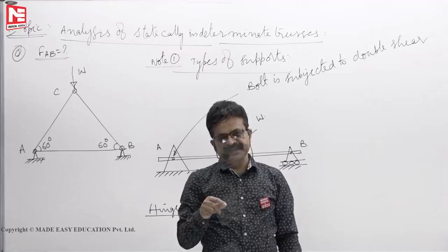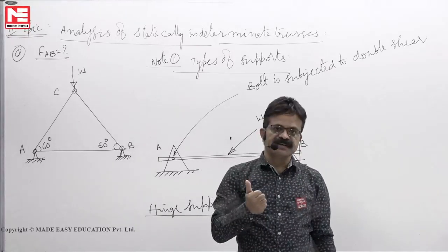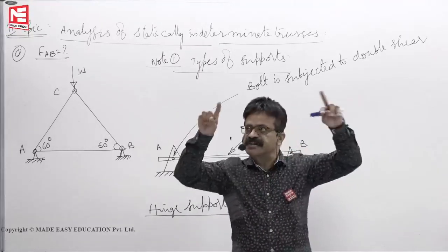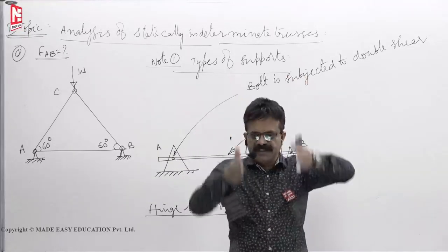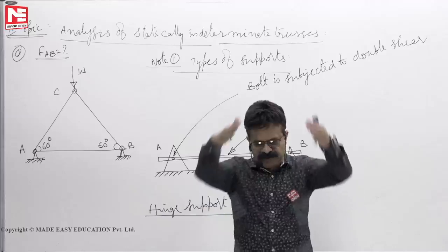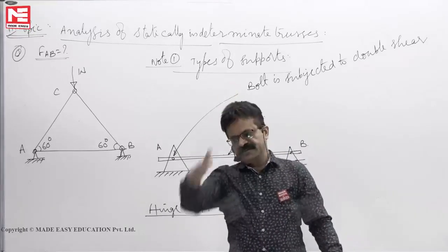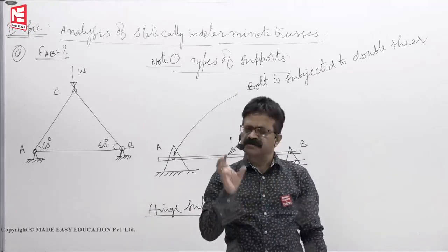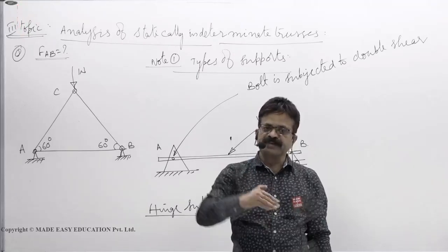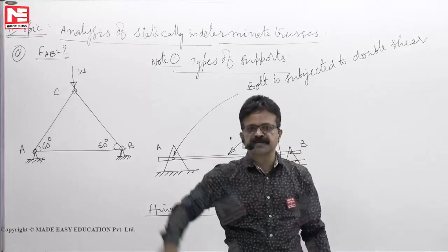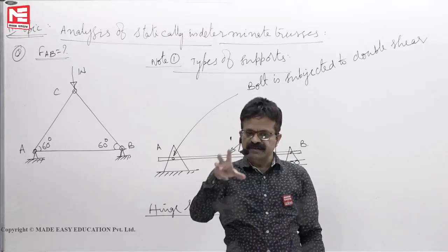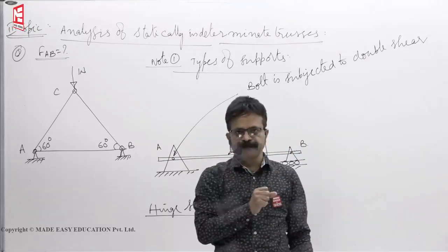In steel structures, you have studied when you are taking web crippling, when you want to test it with horizontal, it will make 30 degrees load dispersion line. Bricks, with respect to vertical, it makes 30 degrees line. So effect is relatively steep in that case. So 30 degrees with respect to vertical, or 30 degrees with respect to horizontal, or 45 degrees, or pressure bulb. Depends on what it is resting.